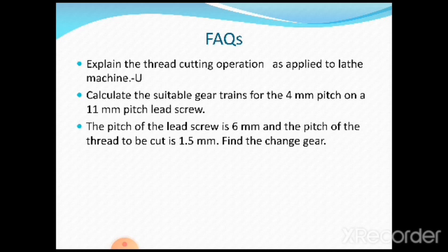The next problem is, the pitch of the lead screw is 6 millimeters and the pitch of the thread to be cut is 1.5 millimeters. Find the change gear. So you try these two problems. If any difficulty is there, we shall have a discussion in the subsequent presentations, or if not, we shall have a discussion when we actually begin with the offline classes.